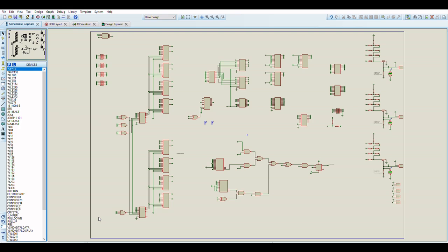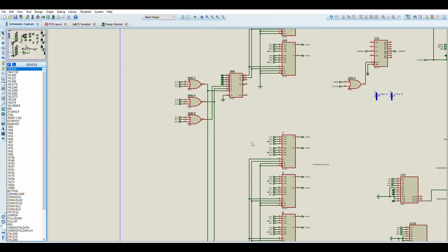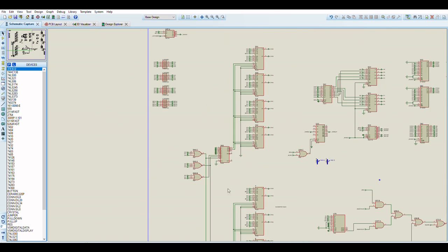Readme 8, which is page 8 on the PDF, and this contains the output pixel pipeline and palette lookup logic. What we have here is some hardware, so we have the headers, which take up to 4 layers of pixel input, here and here.